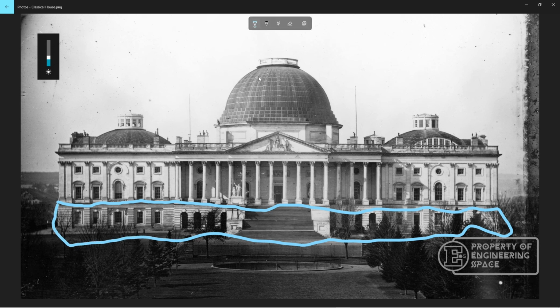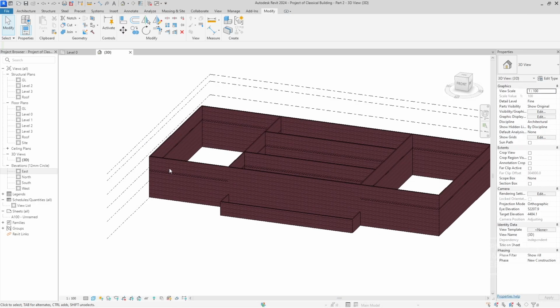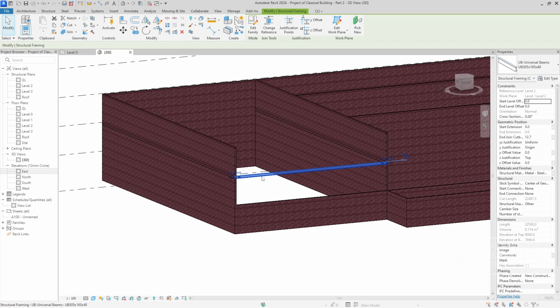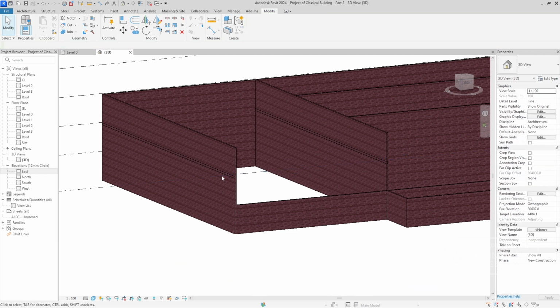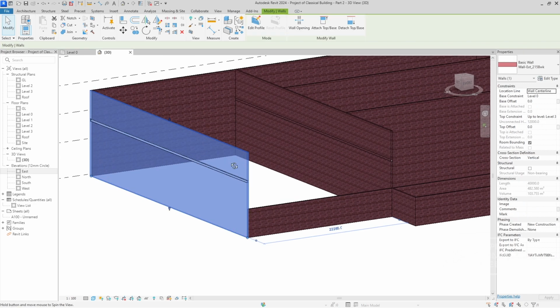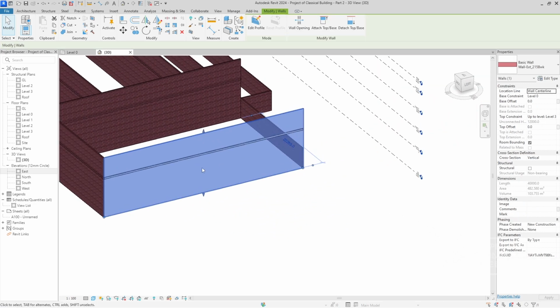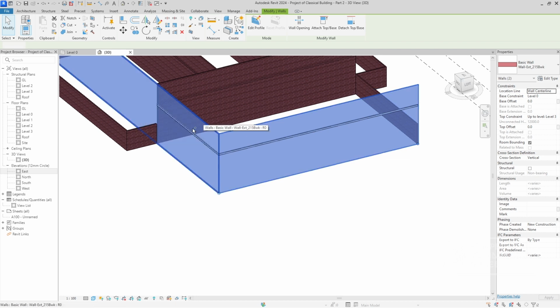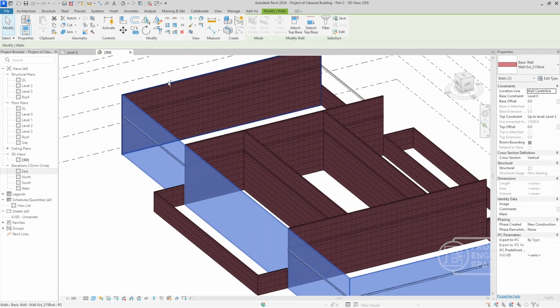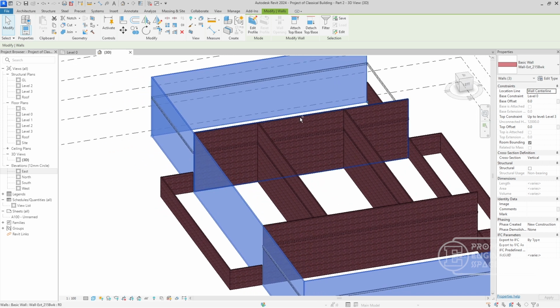Alright, so let me go back to the Revit files. As I also explained in the first video, we also created beams, or structural elements, of the building, and this time we're going to erase everything. We just focus on the architecture part first. So let me erase this one. Okay, let me select the whole wall that contains the first floor from level 0 to level 1.